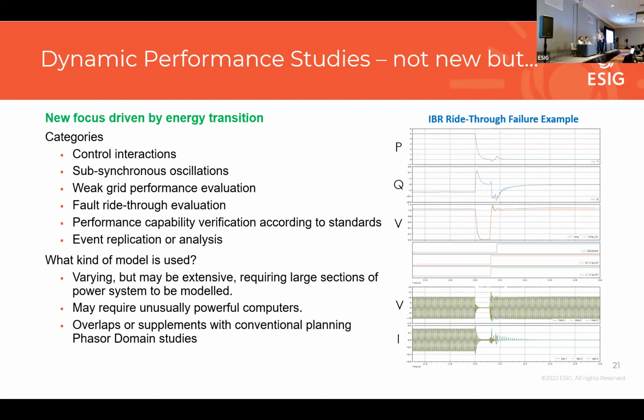Subsynchronous oscillations. Again, these are some of the topics where we mentioned this. That could easily be a whole tutorial, or in fact a week. There's a number of different flavors of subsynchronous oscillations, from SSR, the classic SSO, where you have synchronous machinery interacting with series compensated systems, to now SSTI, where you have inverter-based resources interacting with synchronous machinery, to subsynchronous control interaction, or SSCI, where you have inverter-based resources interacting with series compensated lines.